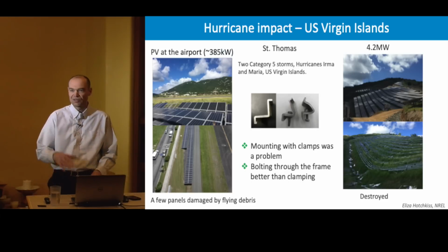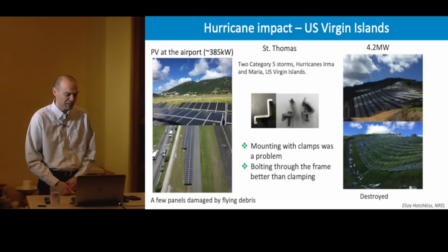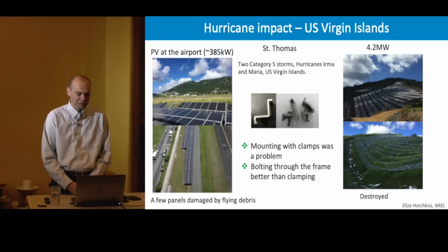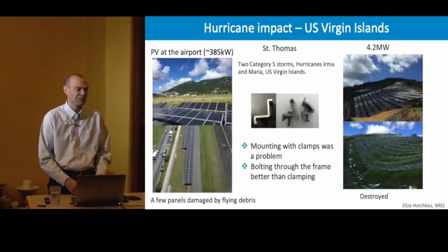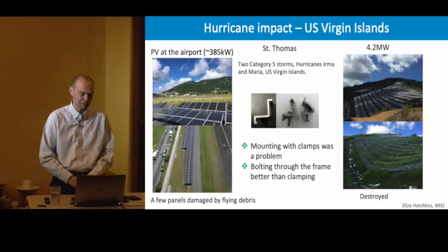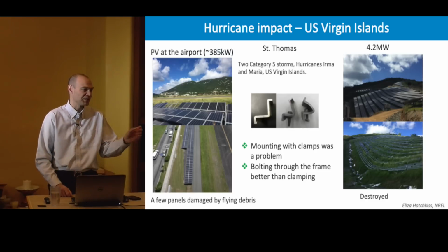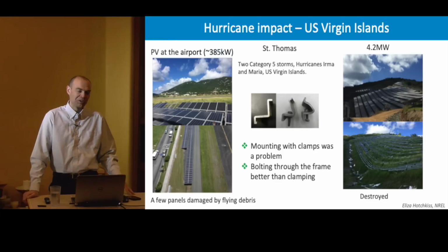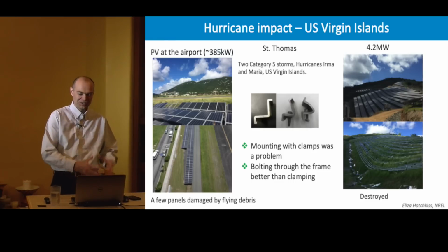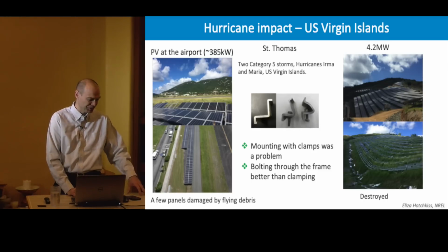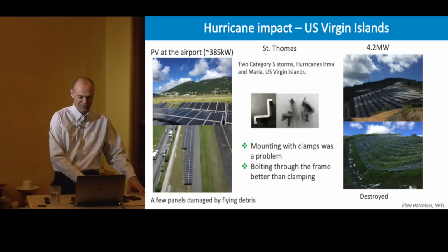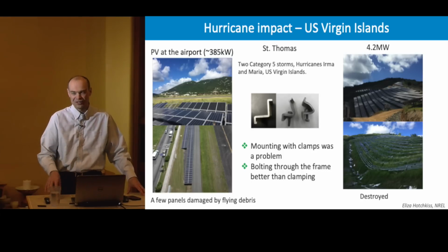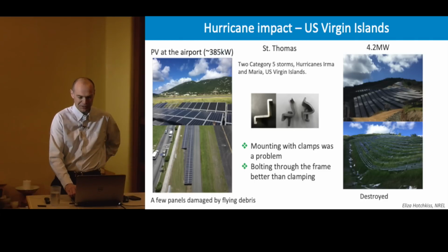Of course, location has an impact. So maybe it was location, but they also found that mounting can be an issue. A lot of those modules were clamped; they were not bolted. You can see how the clamps got deformed from the winds. So that's why I said earlier, installation is a very important piece. It's good if you have a durable design, and it's good if you have consistent manufacturing, but installation is still very important and can have an impact on reliability.